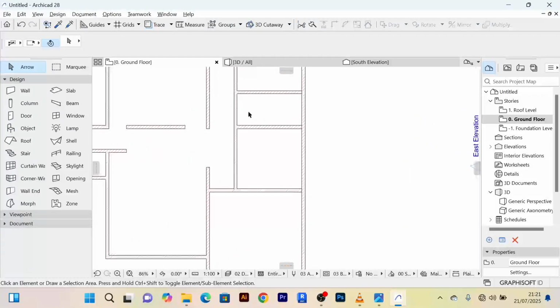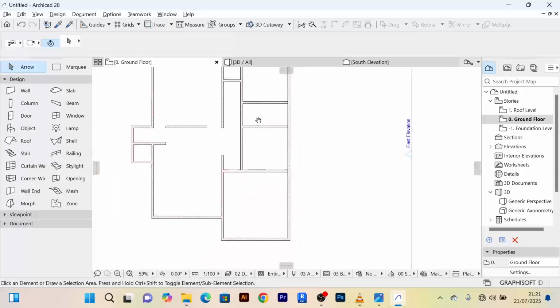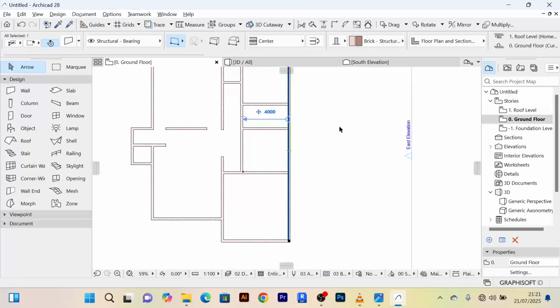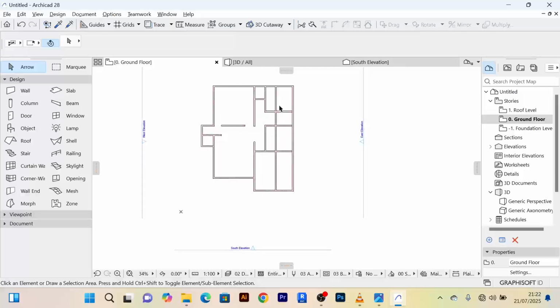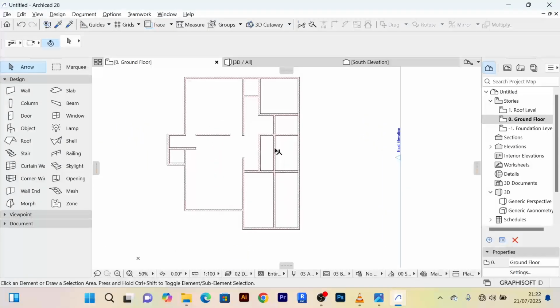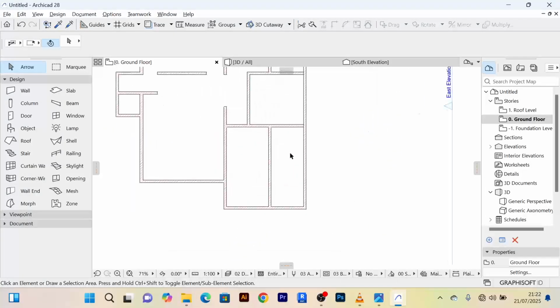First of all, to create that, I'm going to create another wall here. I'll click on this. I'll press Control Shift D. I'll move this by, let's say, 2.4. In fact, I'll move it 2.6, and it will create for us 2.4, just like that. Then I'll delete this part, just like that. I'll delete there, I'll delete here, just like that.